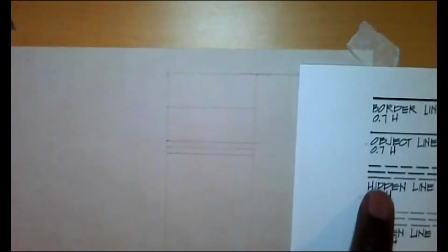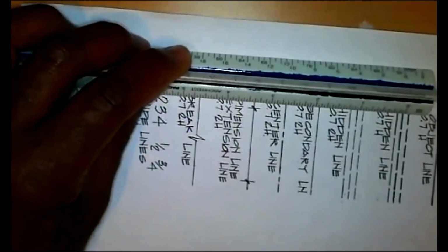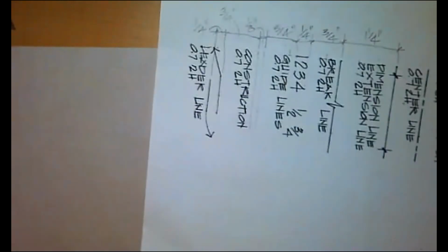T-square up. Good. So again, you notice how I'm ignoring the actual line type. I'm just doing them as continuous construction lines. And that's what you're going to do all the way down, okay? You're going to measure, you're going to scale, and then transfer, okay? Scale, and then transfer, all right? So that's how you're going to start the line type exercise, all right? Thank you.